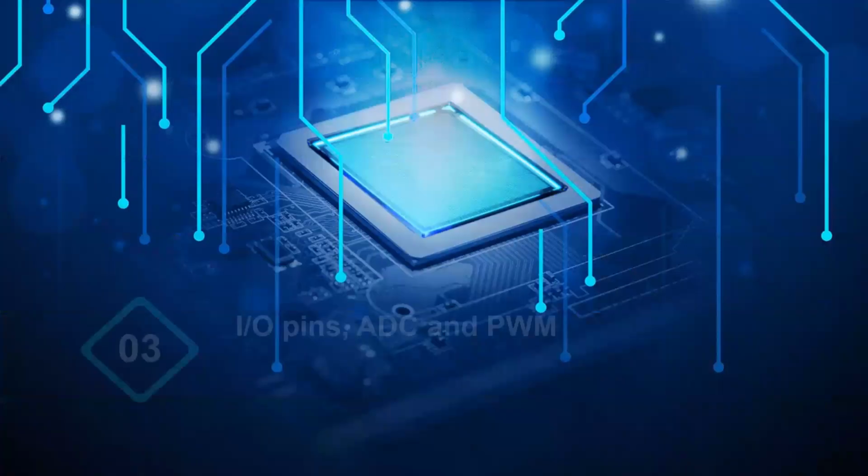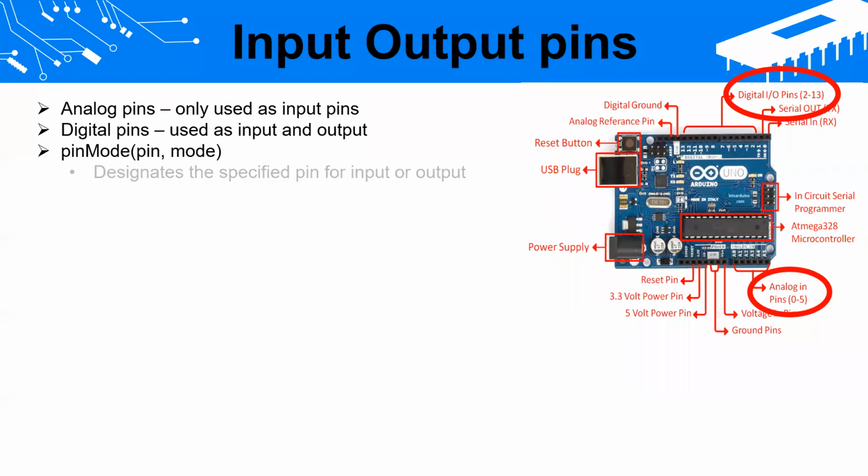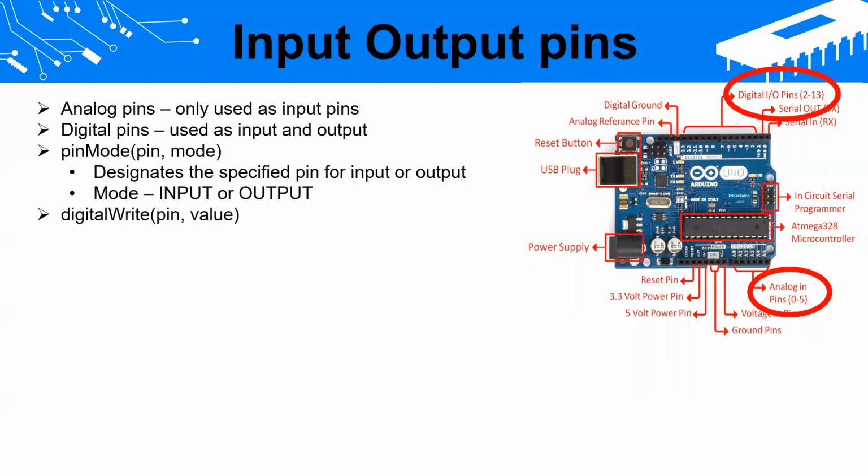Then in lecture 2, we discussed the previous week's lecture. Here we discuss the pins again, what pin modes we have. If you need to take some sensor reading, that is input, so in that case we should set the mode as input. If we need to give some voltage out of a pin, then we should set it as output.